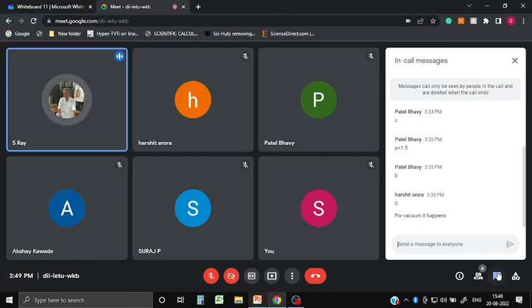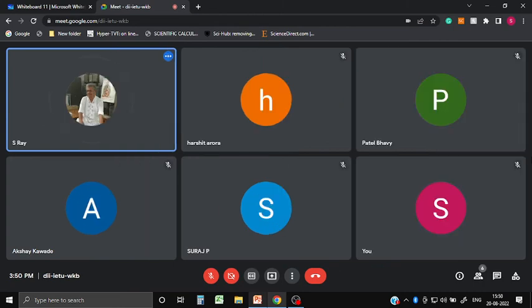If you have higher submergence, what do you expect? It's a flooded condenser, that's why you have a liquid phase residing in it. If your level is high, more tubes will be submerged, and the temperature will be lower.